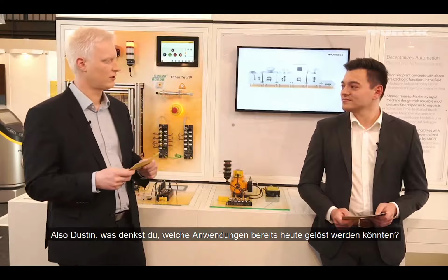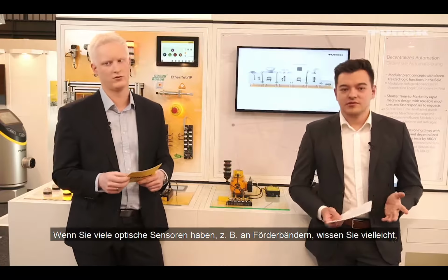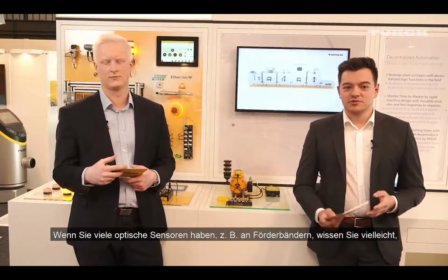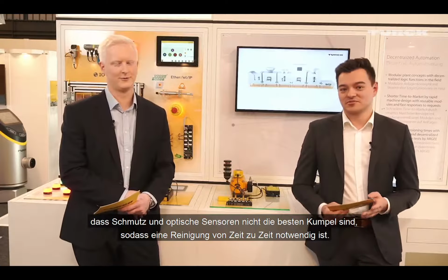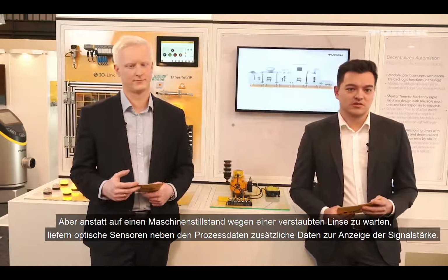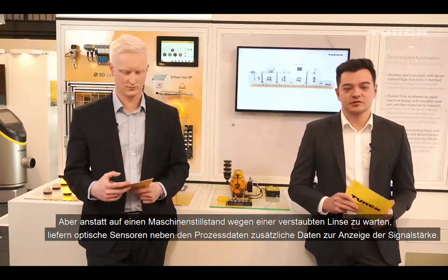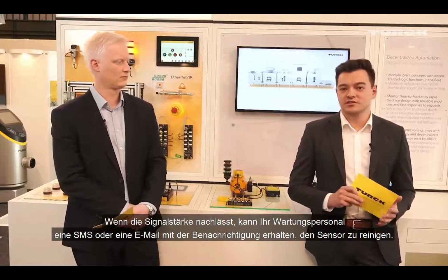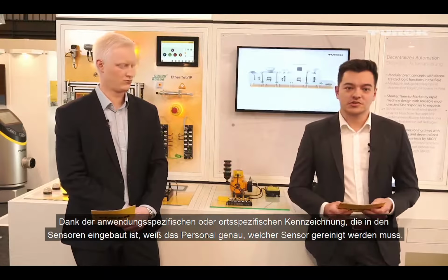So, Dustin, what do you think? Which applications could be solved already today? Maintenance is a good example. If you have many photoelectric sensors, let's say on conveyor belts, you may know that dust and photoelectric sensors are not the best buddies, so cleaning from time to time is necessary. But instead of waiting for a machine downtime just because of a dusty lens, these sensors already deliver additional data to indicate the signal strength beside the process data. And if this signal strength decreases, your maintenance staff can get an SMS or an email from the cloud with a notification to clean the sensor.